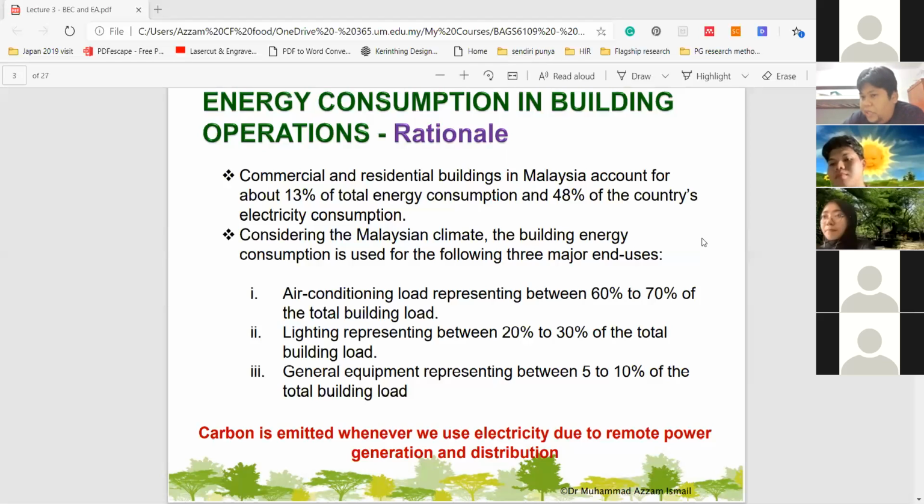So when you receive your electricity bill per month, let's say you use 400 or 500 kilowatt hours per month, about 60% of that is directly connected to cooling. So if you use refrigerators or freezers which are 5-star rated, that will definitely reduce the amount of electricity that you consume. If you reduce the number of times that you open your fridge door, that will definitely reduce the energy consumption, because every time you open it, once you close it back, the fridge will have to cool down again to a certain temperature, isn't it?